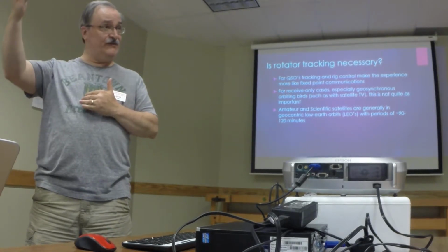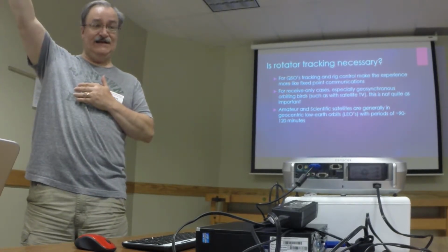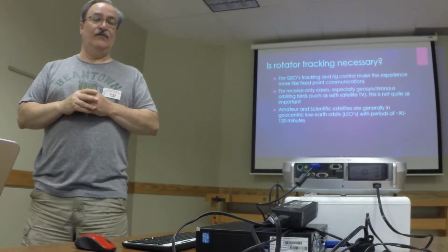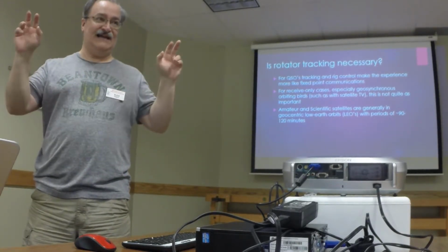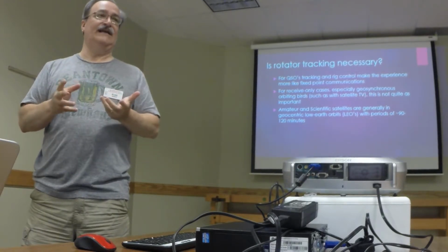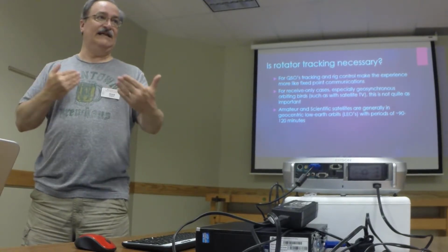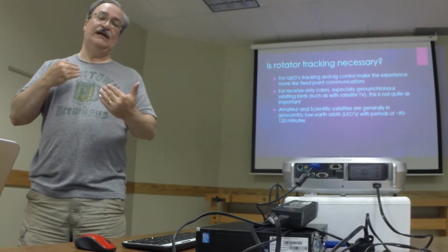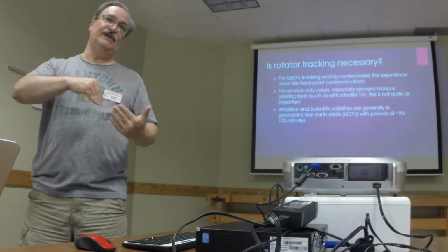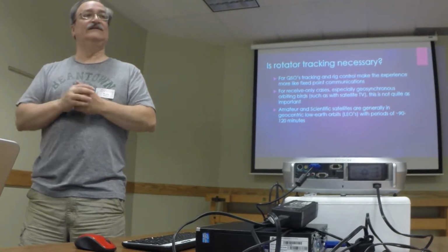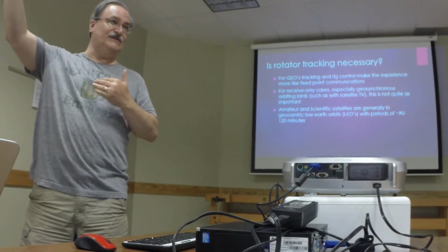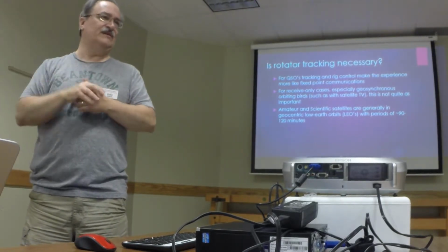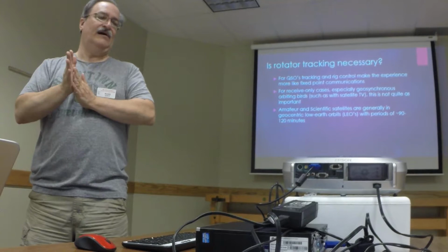They have an uplink frequency to get to the satellite, and then a downlink frequency on the other side. So you have to have a rig. They started coming out with satellite rigs in the 80s and 90s because they could run split. Okay, so they typically don't go cross mode, but they run split between 2 meters and 70 centimeters. So you may go up on 2 meters and down on UHF, or vice versa. Typically, the lower frequency is going to be up.